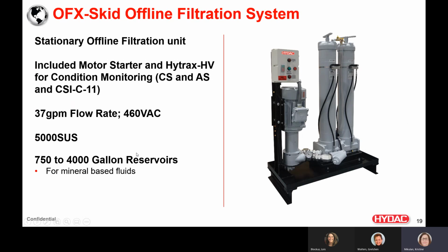Now for customers that have a very large reservoir permanently installed in their system, we can use our OFX skid offline filtration system. So this is going to be a stationary offline filtration unit with an included motor starter and our Hydac high viscosity condition monitoring system that includes both the CS1220 and an aqua sensor for water saturation, as well as our CSI C11 contamination sensor interface for data acquisition and retrieval.